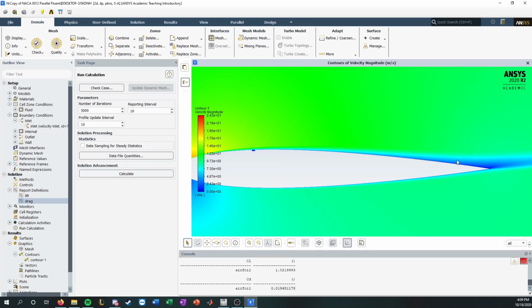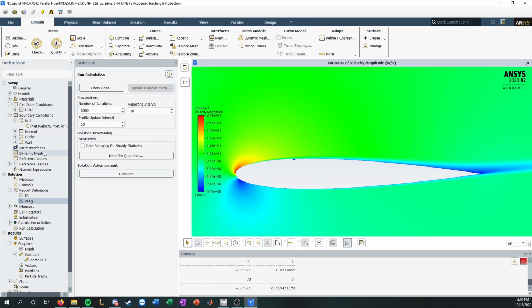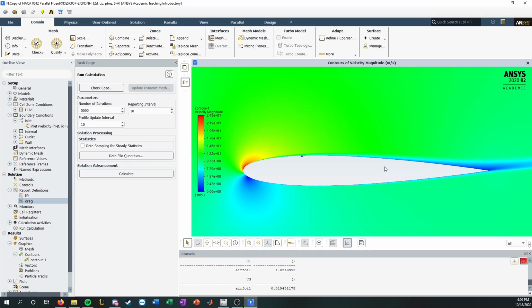And so hopefully this demonstrated and proved to you guys the difficulty of trying to simulate a vortex generator in two-dimensional and in steady state and using these turbulent models. So I'd highly recommend, if you're interested in doing vortex generator or boundary layer manipulation studies, it very likely has to be three-dimension. When you do it in three-dimension, you can take a planar contour that will produce something like this, but the solver has to take the vortex into consideration as a three-dimensional effect, and it probably has to be transient if you really wanted to get a good understanding.